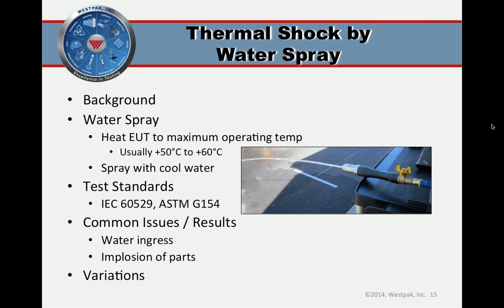If the sprinklers come on or there's a sudden thunderstorm or something like that, the unit could be exposed to cool water, and generally the water temp will be somewhere around 15 to 20 degrees C, and you'll very rapidly cool the product. It's truly a thermal shock. This is discussed in the IEC 60529 standard. It was just revised, and they added a test somewhat covering this. Again, not applicable to many products, but very applicable to some products.